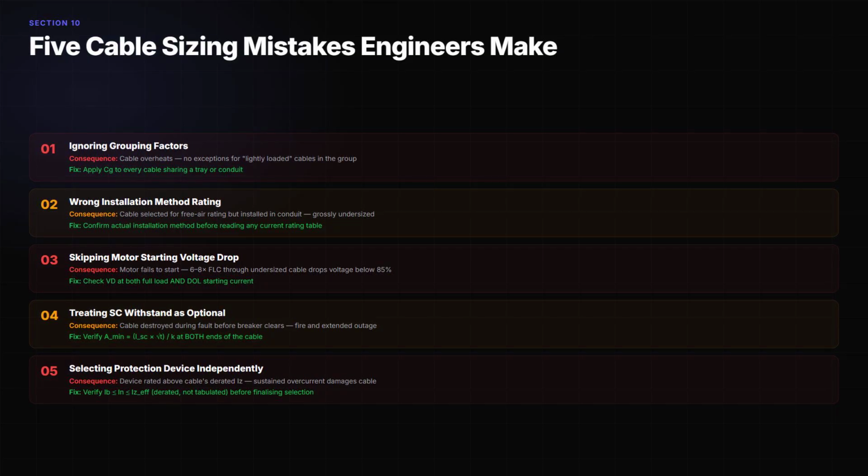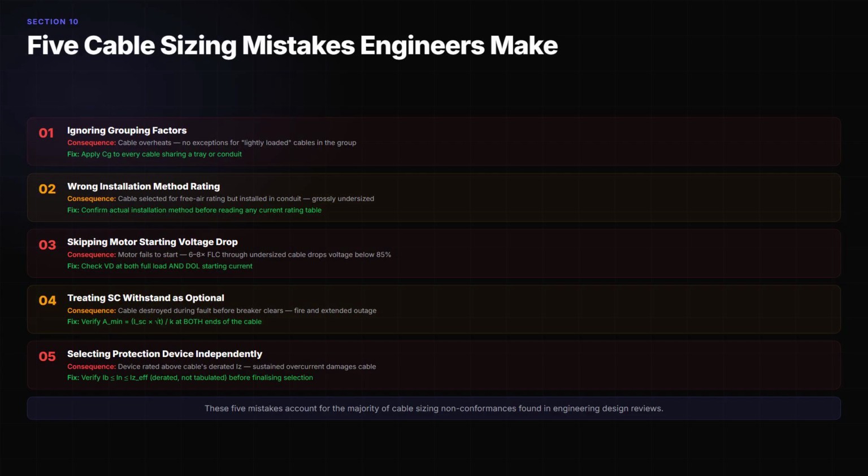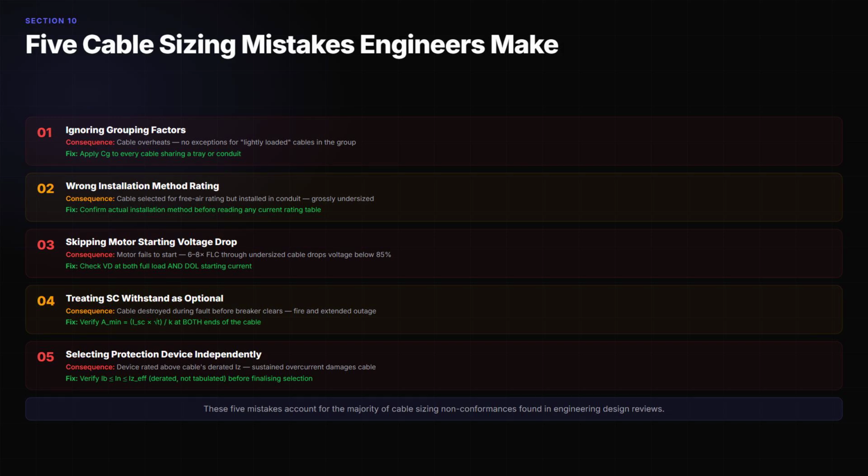Mistake 3: skipping the starting voltage drop check on motor circuits. Full load voltage drop compliance does not guarantee starting compliance. Mistake 4: treating short circuit withstand as optional. It is a mandatory criterion under every major cable sizing standard. Mistake 5: selecting a protection device independently.